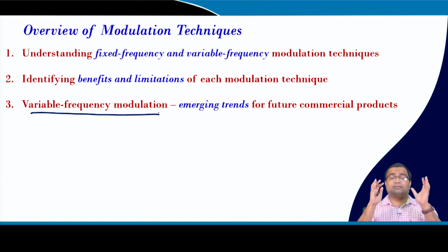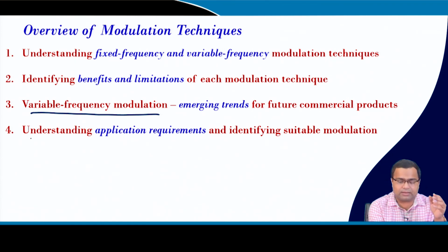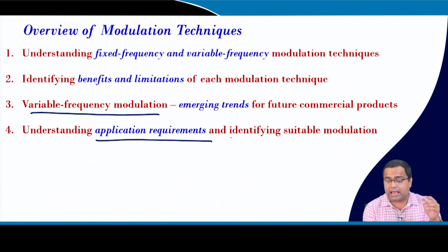And we have also discussed that in such cases the event based sampling in variable frequency control can offer significant stability and performance benefits over its fixed frequency counterpart, and from a future commercial product point of view, it can be a potential solution. Then we understood that we need to understand the application requirement and identify the suitable modulation technique.